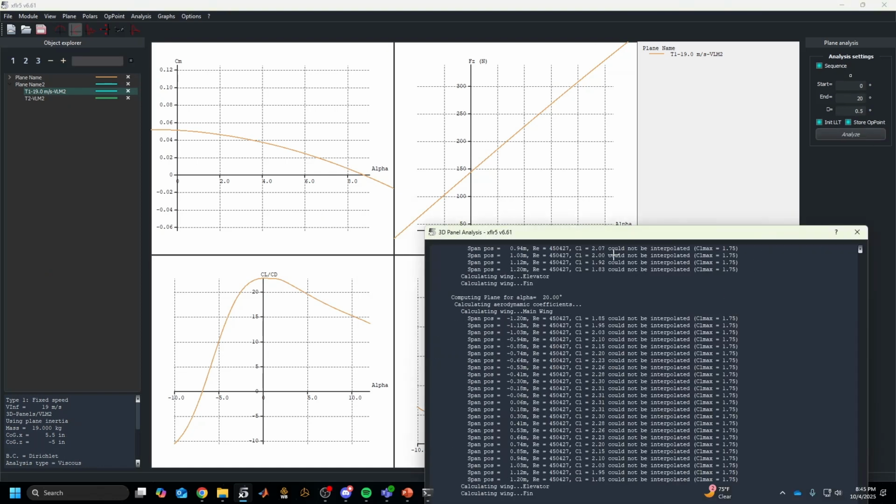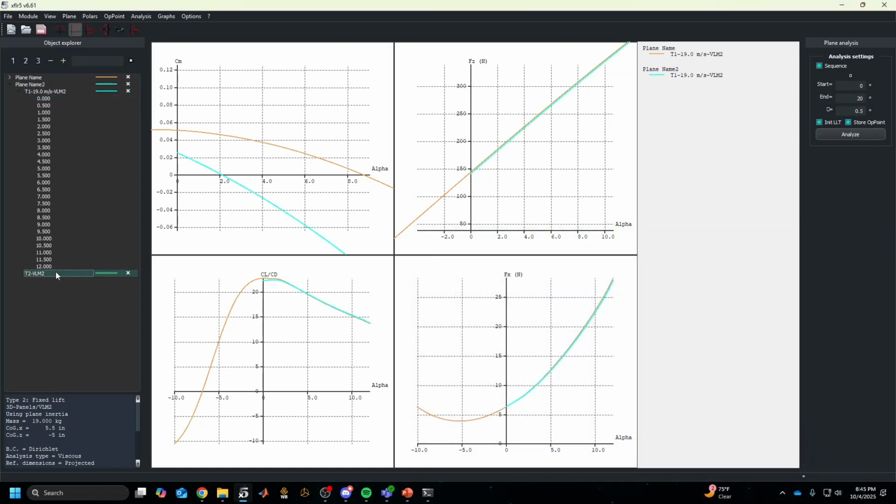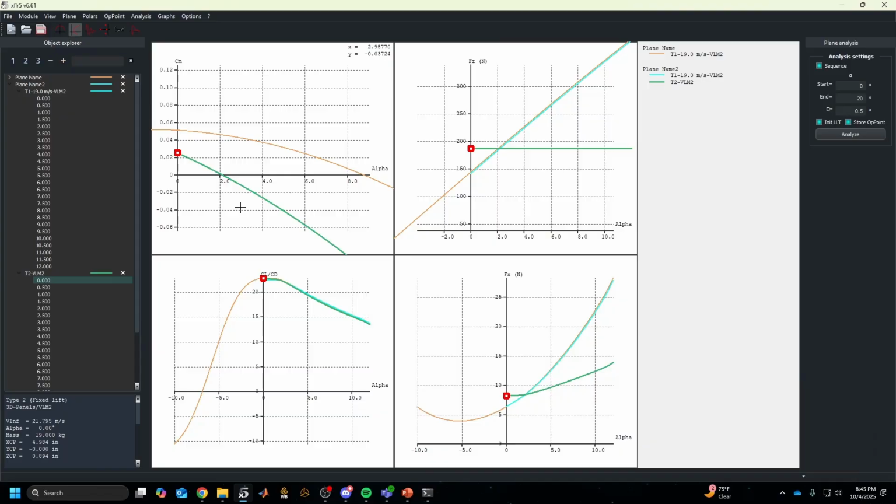And you guys can also, if you're not getting enough performance out of your tail, right? You're not moving your line enough. You can make your plane bigger, or your tail bigger, or you can move it farther back, right? You can make your tail volume coefficient even larger, right? That's a way you can solve this too.